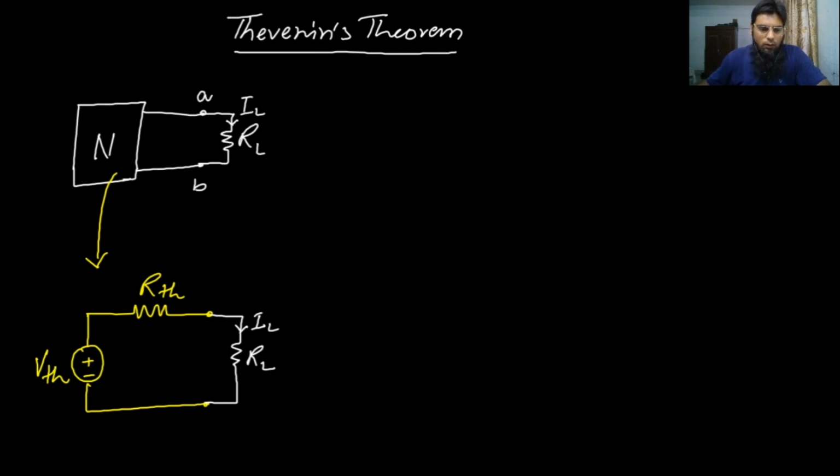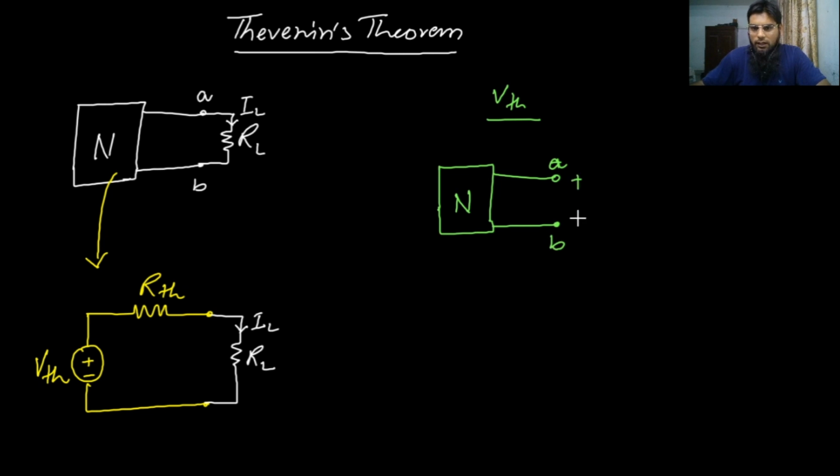So what is VTH? We have this network N, and if we open circuit the terminal AB and calculate this open circuit voltage, it will be equal to VTH.